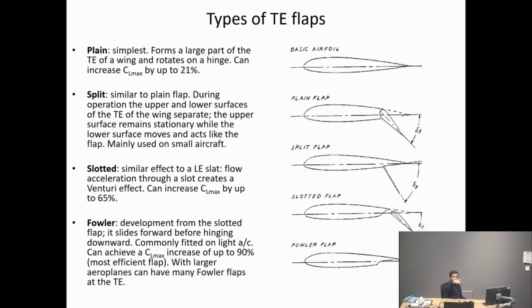So it has two effects there. First of all, the fact that the flap goes downwards, we are increasing the camber of the main wing. That's one effect. But the fact that you have a slot means the air will rush through the slot with high kinetic energy, and then it goes on the upper surface of the flap, energizing the boundary layer of that flap, and therefore it allows it to deflect more without separation. Because just like a wing, the flap can also separate and can stall. We don't want that. That's not a good thing. But the fact that you have a slot allows the flap to go to higher angles, and therefore you are also helping the aircraft to go to much higher camber, and therefore much higher lift.